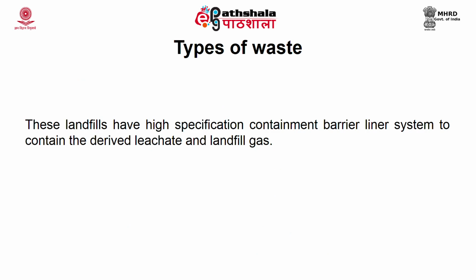These landfills have high specification. For example, when you discuss the hazardous landfill or secure landfill, you should have a very good containment system. The barriers or the liner system should be so well designed, so that the leachate or the landfill gas does not escape out, and it should not affect the environment.